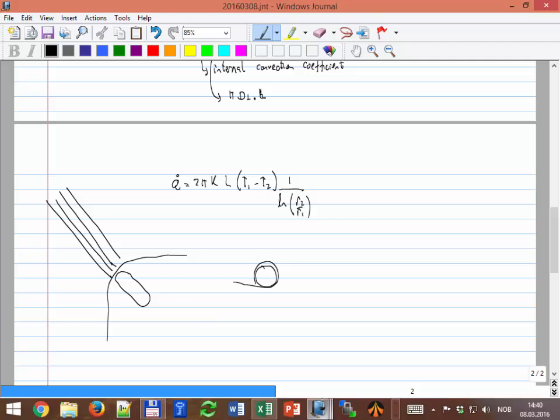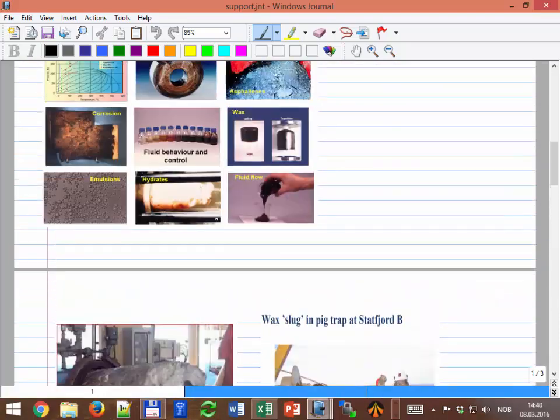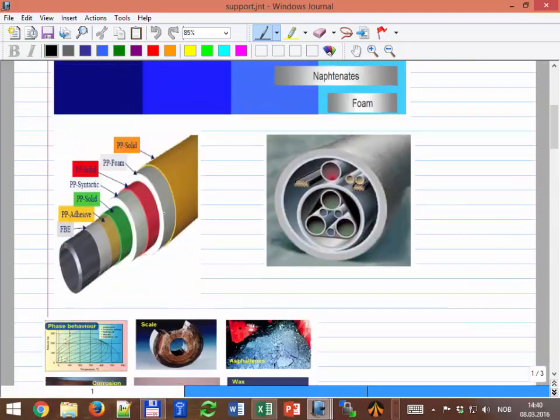But as you see on the picture, I think I showed you yesterday a picture, you might have more and more layers, but then the pipe becomes bigger and more and more expensive. One thing important to note is that the density of this material is actually lighter than water. So when you put these pipes, if you leave them without any support, they will tend to float, to go up. So you have to put some concrete supports to add weight to the pipe. Usually, instead of putting plastic insulation, they also do the insulation with cement.